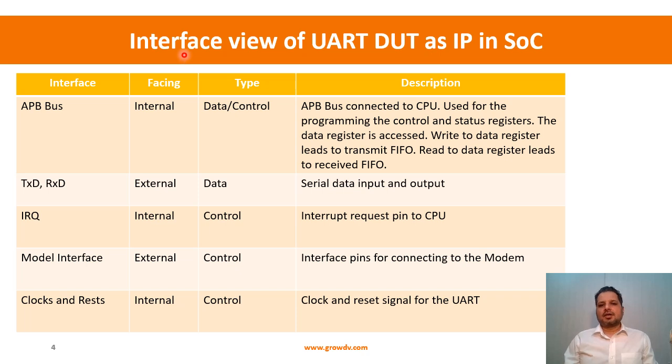So let's summarize the interface view of the UART DUT as an IP in an SOC. That's the picture we are trying to get to, right? We have an APB bus, and what I mean by facing is whether the ports we are talking about go out of the chip or remain within the chip. So this remains internal. All the APB, AXI, AHB buses are SOC internal buses, so they remain within the SOC. Those interfaces don't become pins on your chip package and go out externally. That doesn't happen.